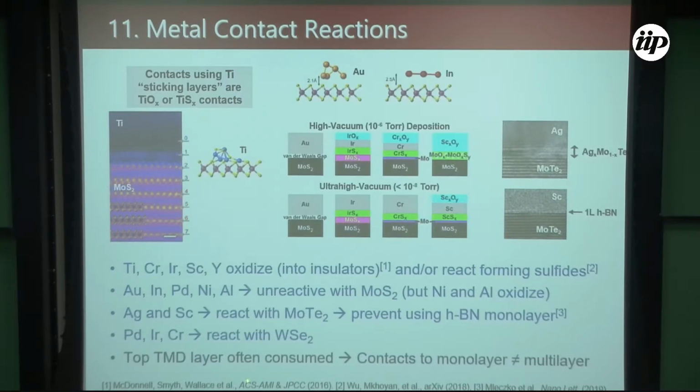And there's much work by Bob Wallace at UT Dallas going back now at least 3 years, showing how this happens. He's done lots of XPS. He's done lots of elemental analysis. This is actually a more recent paper on arXiv from Andre Mkhoyan from University of Minnesota. He doesn't see the oxygen here, but he definitely sees the titanium eating. It's literally eating away the MoS2. Even calculations show that titanium just goes and eats at the MoS2. Of course, gold and indium, by the way, don't react.